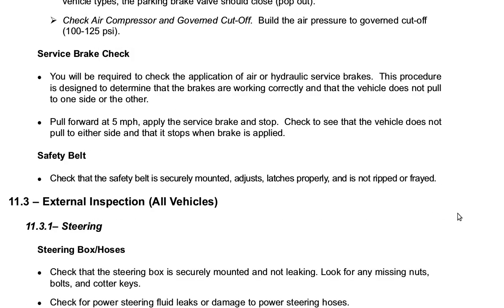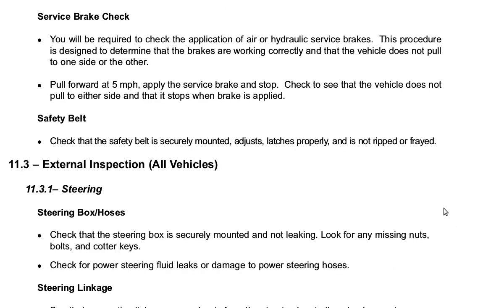Service brake check. You will be required to check the application of air or hydraulic service brakes. This procedure is designed to determine that the air brakes are working correctly and that the vehicle does not pull to one side or the other.